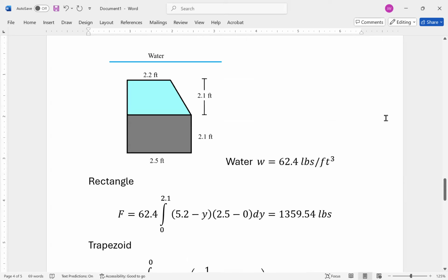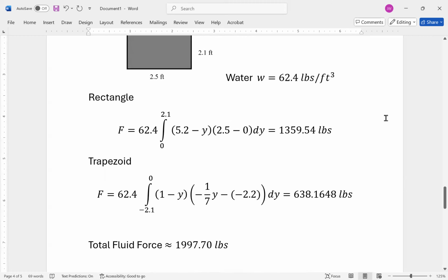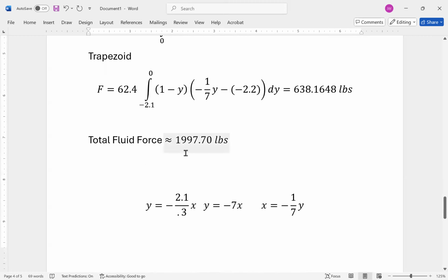You break the window and you crawl out the window, or you roll down the window as your car is going into the water and then crawl out the window. Because if you don't, then trying to force the door open is just way too hard as long as there's air inside of the vehicle. We're talking about 2,000 pounds of force being applied to the outside. But again, once the interior of the vehicle fills with water, then that force is being applied to both sides, and so it's much, much easier to open the door.